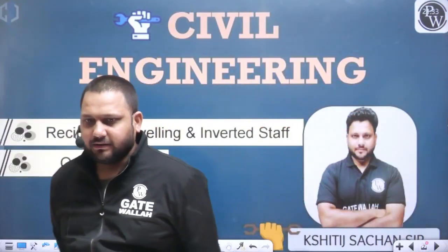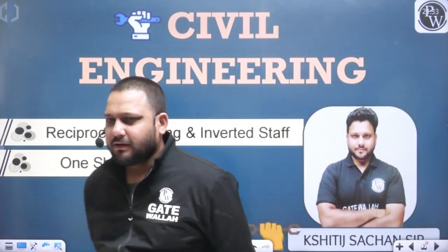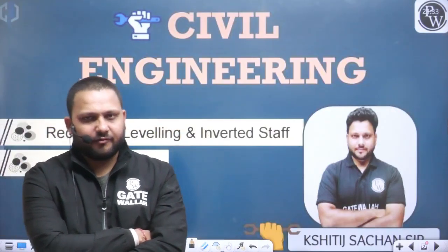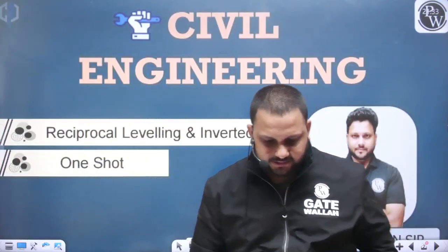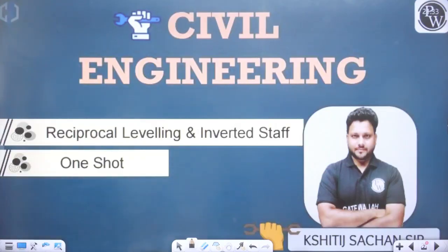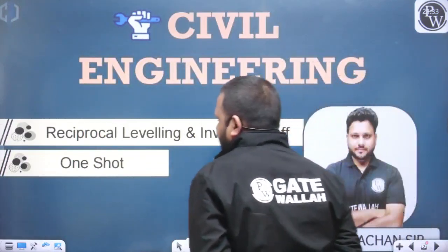I hope after this class you will complete that home assignment, and you can check your calculation on your own, because for the rise and fall method we have the arithmetical check. The algebraic summation of all the back sides minus the algebraic summation of all the fore sides should be equal to the algebraic summation of rise minus the algebraic summation of fall, and it should be equal to last RL minus first RL. So that you will do. And then we started our discussion of geodetic leveling.